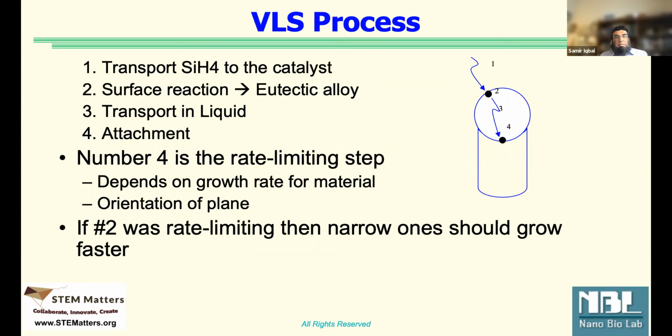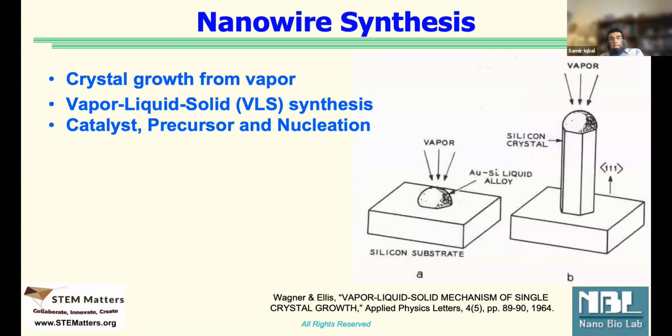So that crystalline structure, or that binding of silicon at the bottom interface, results in the formation of a nanowire. So it's kind of brick by brick. If you think of it, I would put down bricks and keep on climbing on top of the bricks, and I can make a tower and I'm sitting at the top of that tower. So that gold particle would absorb the vapor and the silicon would travel by diffusion, by random transport.